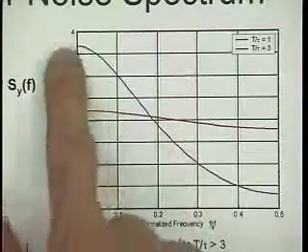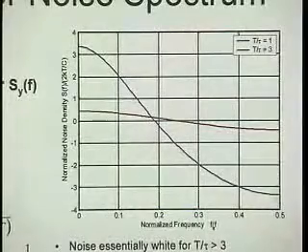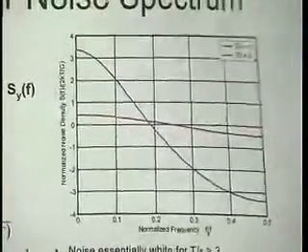Okay, if we didn't oversample, then the spectrum isn't white. But again, this blue case, find a reason why you would want to do this. So that's the spectrum of noise and also the spectrum of sampled noise. In the end, it turns out everything's simple. It's kind of white, and sometimes it's really important to know that also. But really, why is it so? Well, it's not so straightforward. So I hope you make sure that you understand that, and if you have questions, ask them now or during the office hour or whatnot.